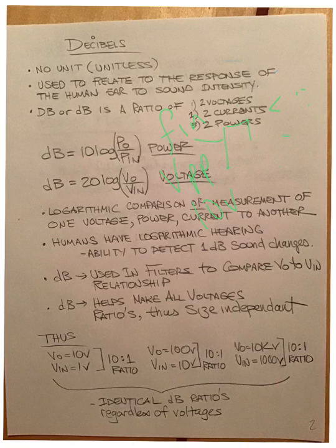We're building just straight low pass, high pass, and band pass filters, and we have no power supplies. These are not what they call active circuits. They are passive circuits, meaning that the resistors and capacitors are not powered. There is a voltage peak to peak going into them, that is true, but there is no voltage powering them like you might have with a transistor or with an operational amplifier. So, more information than you might have needed, but good information.